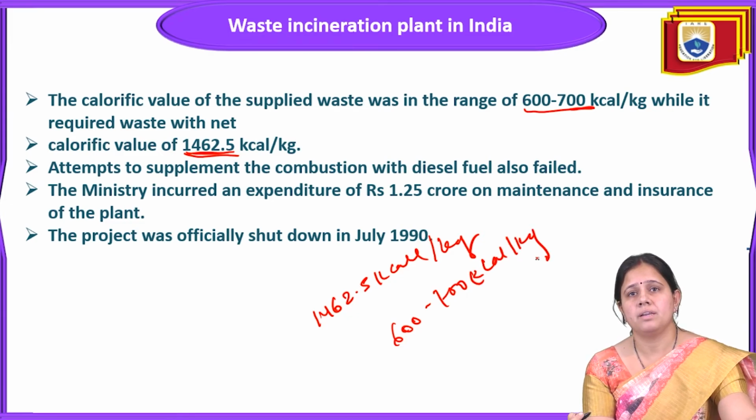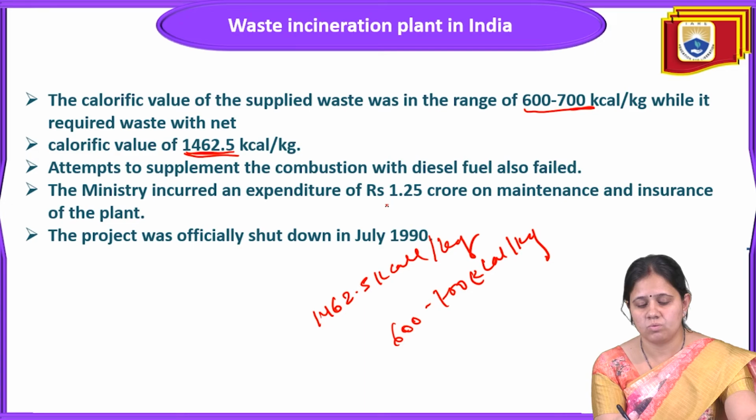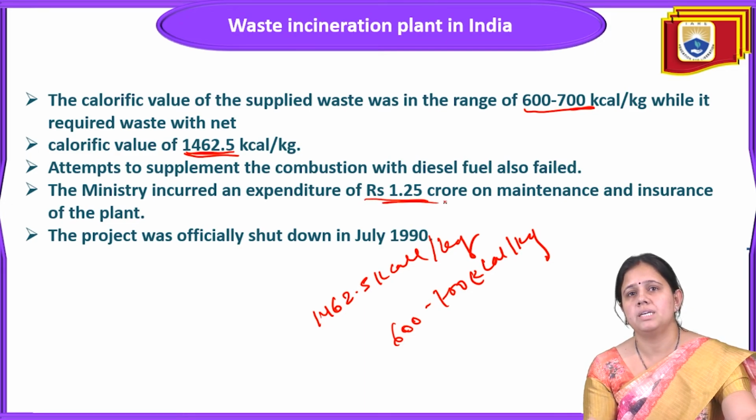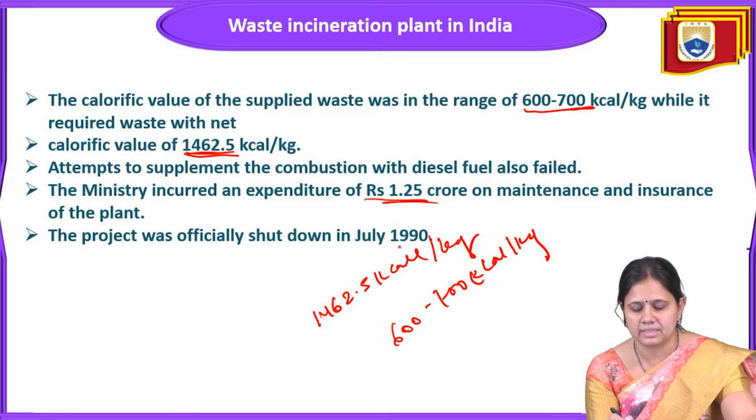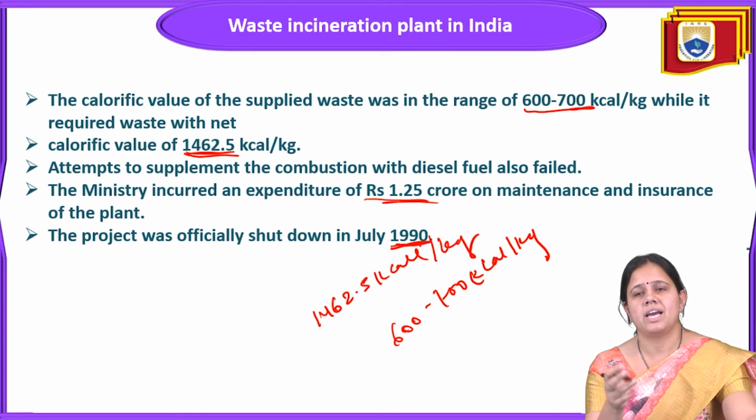So what happened? Some attempts were made to supplement it by adding auxiliary fuels, but those also failed. The ministry incurred an expenditure of rupees 1.25 crore on maintenance and insurance of the plant, but this project was officially shut down in July 1990. So with this lesson, we have added some considerations while designing an incinerator plant.